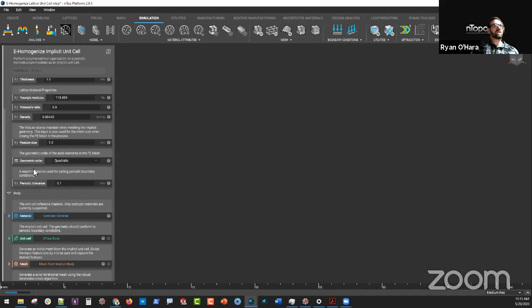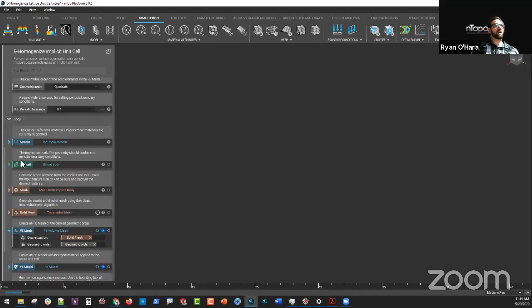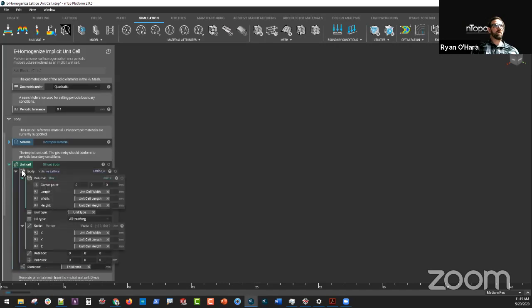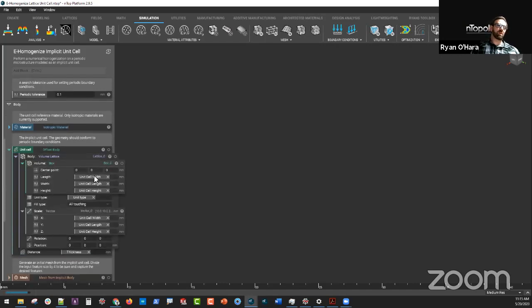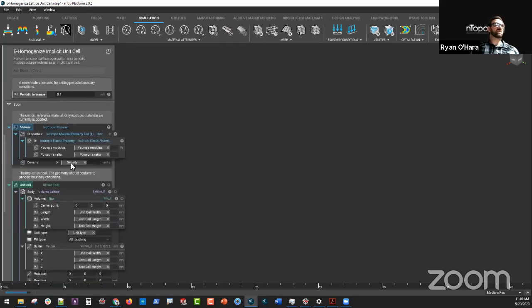As we're doing that, you can see how we've defined all these inputs, and they're just from the blocks associated with the lattice. You can see these variable chips showing up, and we implement those by right-clicking and selecting them and saying make variable. In this case, I've already made a variable, so it's grayed out, but that is available. The other key here is that we are providing just density as a material property into the FEA analysis of the lattice itself. So I guess that's how the density is used in this scenario.